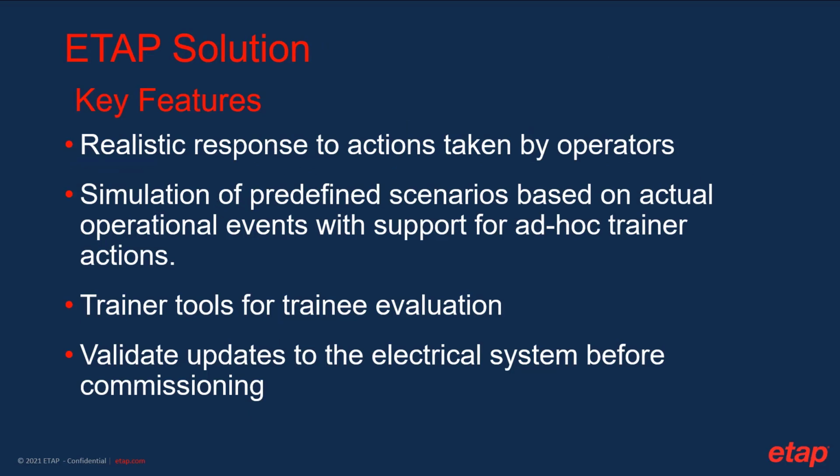Some of the key features include a realistic response to actions taken by the operators. This is because it is a model-based solution, so you actually get that system response, not just seeing if the circuit breaker is opened or closed. We have simulation of predefined scenarios based on actual operational events that happened in the past, but also support ad hoc trainer actions. So ad hoc, a trainer can go and inject an event or a trip signal during an actual training session.